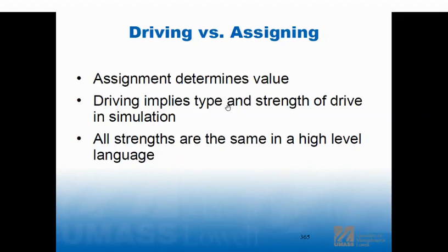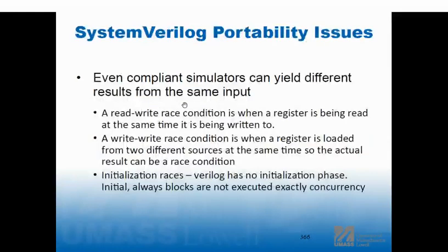So, all right, I'll give you one last example of this. A lot of times when we do ASIC design, we do an FPGA prototype of the logic, and we take that logic block, forget about the pads, dump it into the FPGA tool and run the FPGA tool. Don't even think about the pads. Because if it didn't quite work as far as pad drive strengths, I don't care on my proto board, right? On my reference design, I care about it in the ASIC, and I know those pads are going to have very different characteristics between the FPGA and the ASIC. So this is more notional than anything.